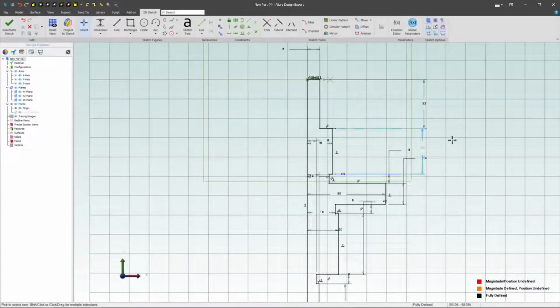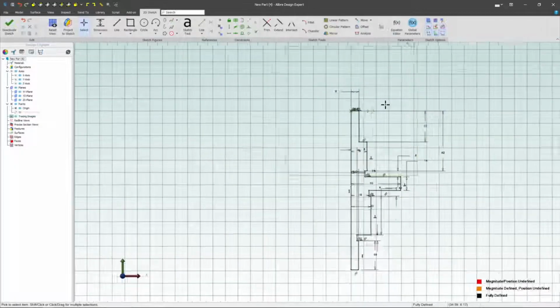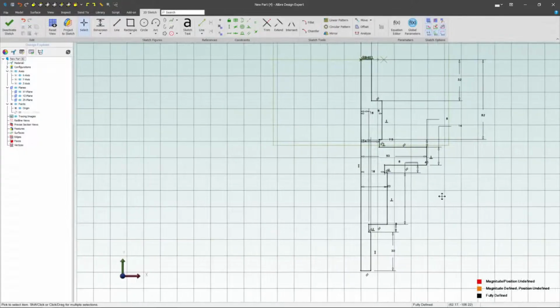So another way of dimensioning that is harder to follow along with in the video is to all go from one point to the next. And that way, by having all of my dimensions be referenced off of the end, all of the plus or minus 1s can be not relative to one another, right? We break the chain by referencing the same edge in all of our tolerances. So that is something to keep in mind in the future for design intent. But of course, that would be harder to follow along with, so we stuck with chain dimensioning here.